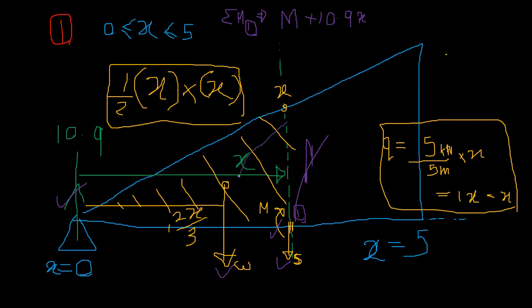That's going to be anti-clockwise. You remember this point? Around this point, this load is going in anti-clockwise direction. So that's going to be negative. W is this x squared over 2, into the length, which is 2x over 3. So that's going to be 2x over, sorry, x cube over 3, right?